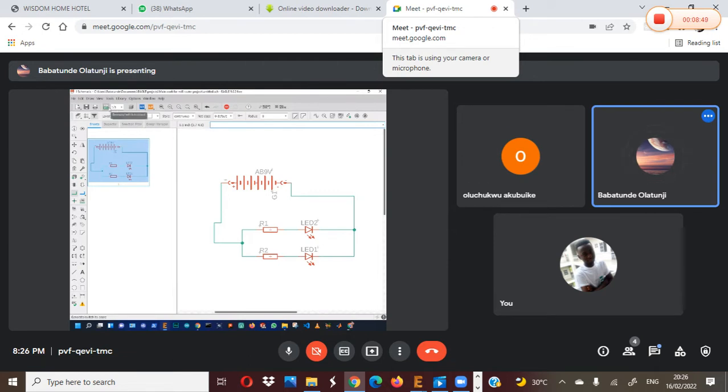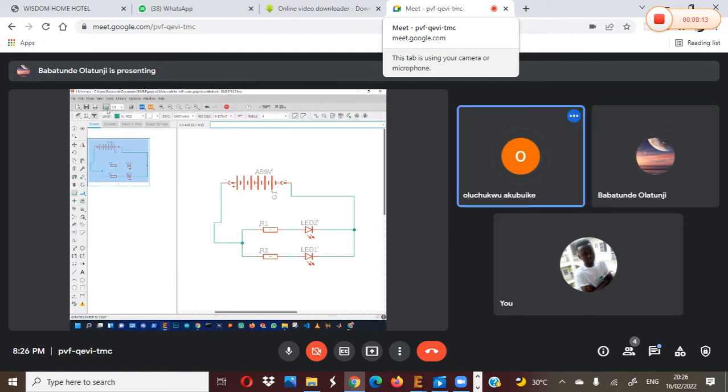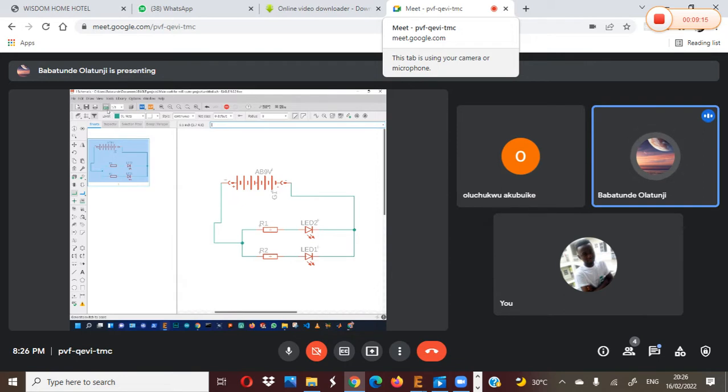So at this top menu, you'll be seeing some options like save, print. Here you'll be seeing generate, switch to board, where you'll be seeing the SCH and BRD. And if you notice, the color of this board is green. It's just giving you an idea that you're actually in your schematic environment. So if you click on this, it will take you to your PCB.